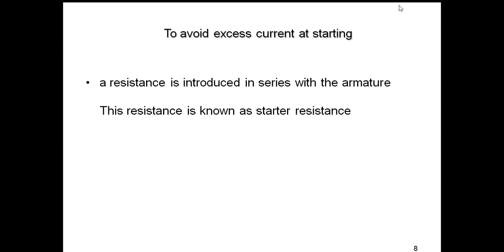So in order to avoid this large starting current, a resistance is introduced in series with the armature, and this resistance is known as starting resistance or starter resistance.